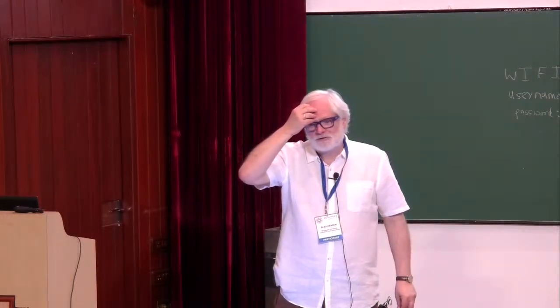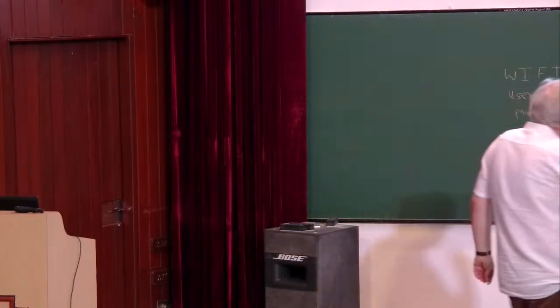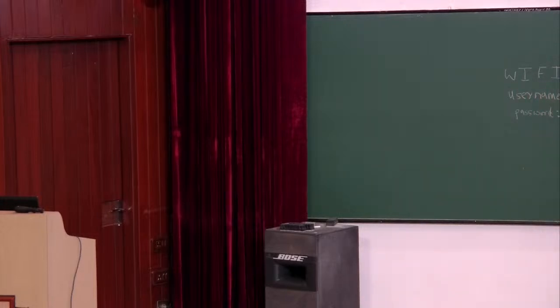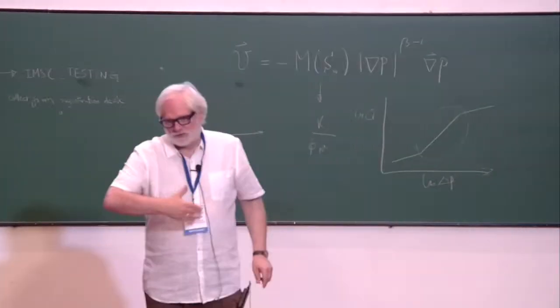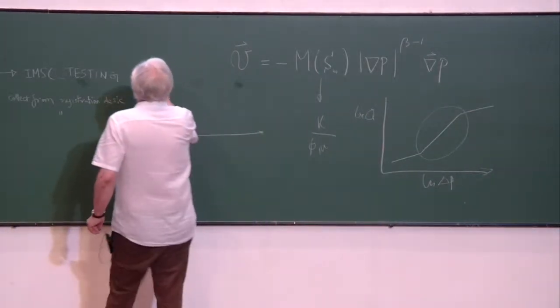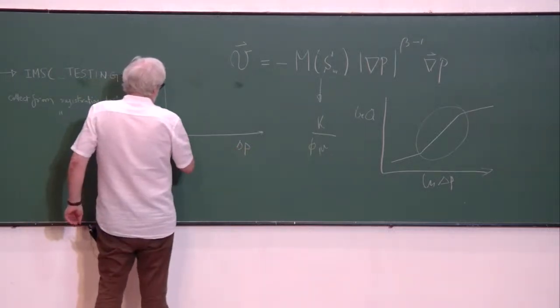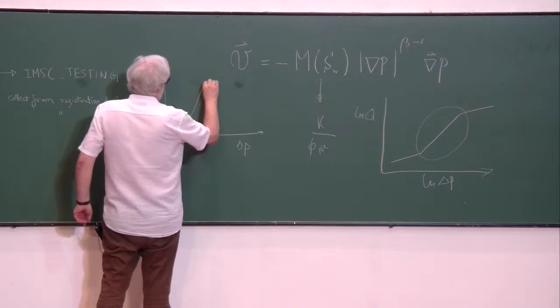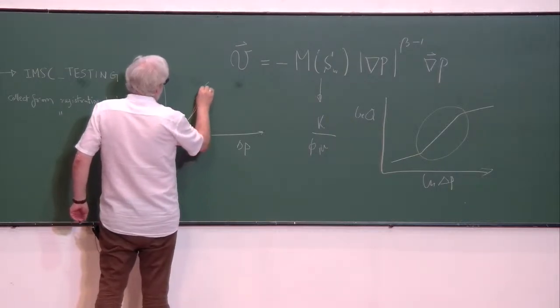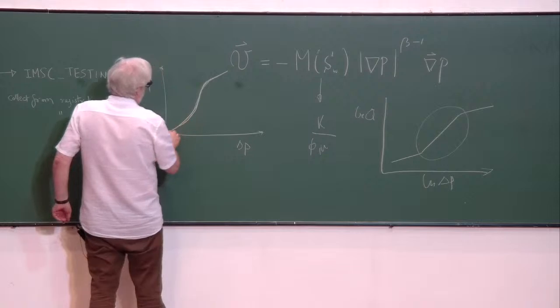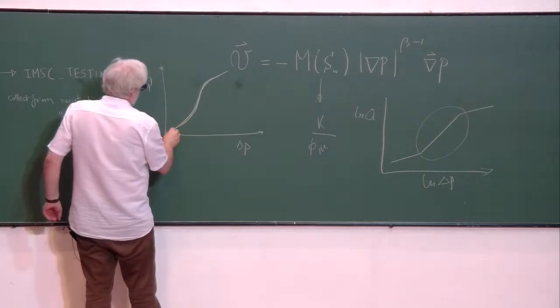Then would the two lines, that means the initial slope and the terminal slope, pass through 0? It depends. If the system is percolating, it passes through 0. If it is not percolating, that means you have interfaces that block, you have a threshold pressure. Typically Q would then be something like this, and it would end up down here.